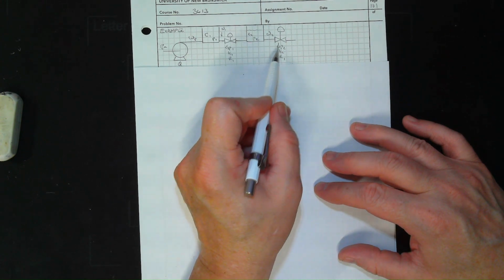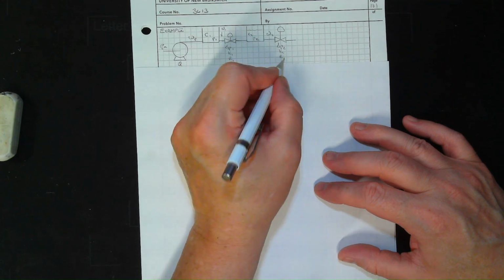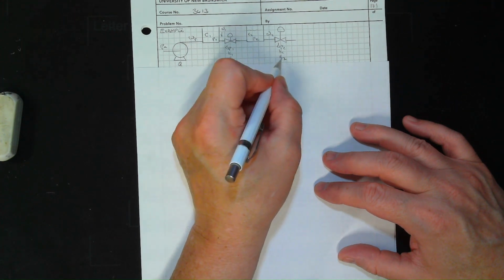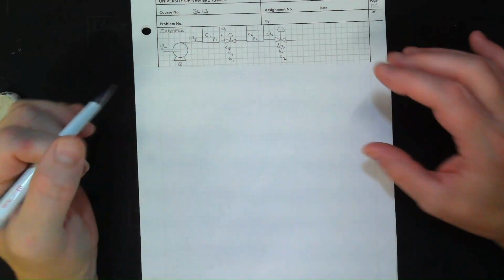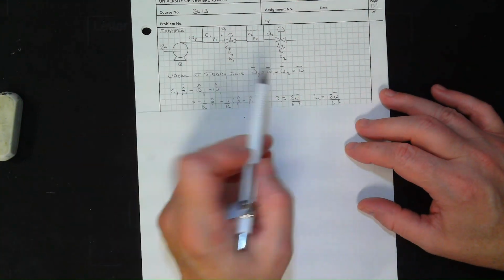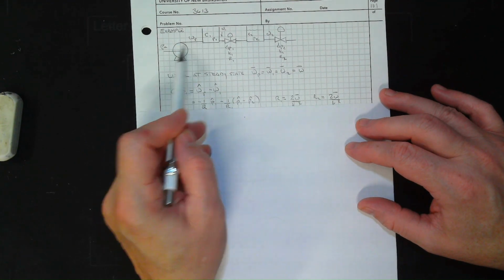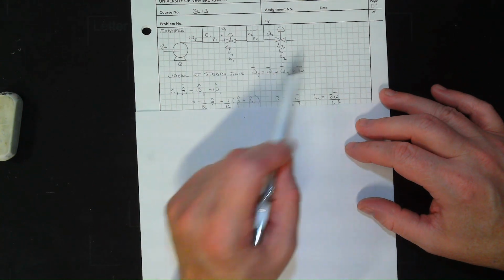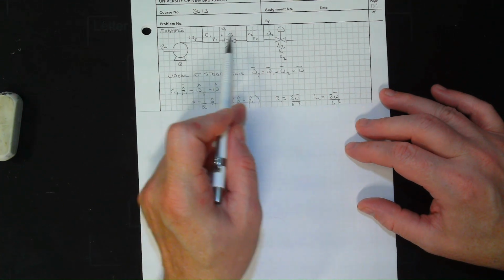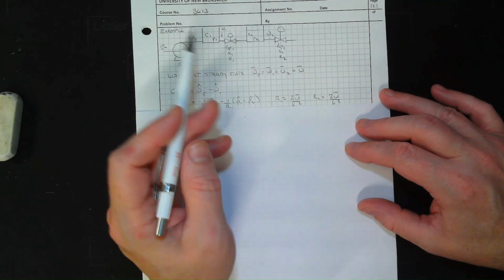And here we have this valve set to the same. This is R2. K2, R2. All right. So we have all of the stuff relative to being linearized. We're just going to go directly to the perturbation variables. Okay. So everything's to be linearized here. We're just going to do everything at steady state. So the pump flow omega 1, omega 2, is just generic omega.